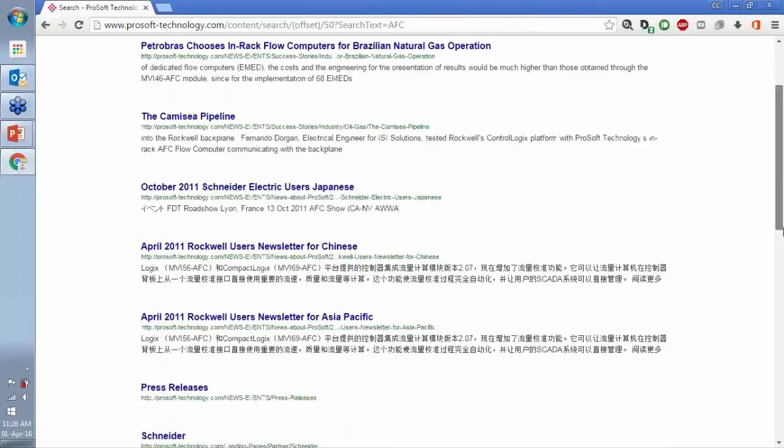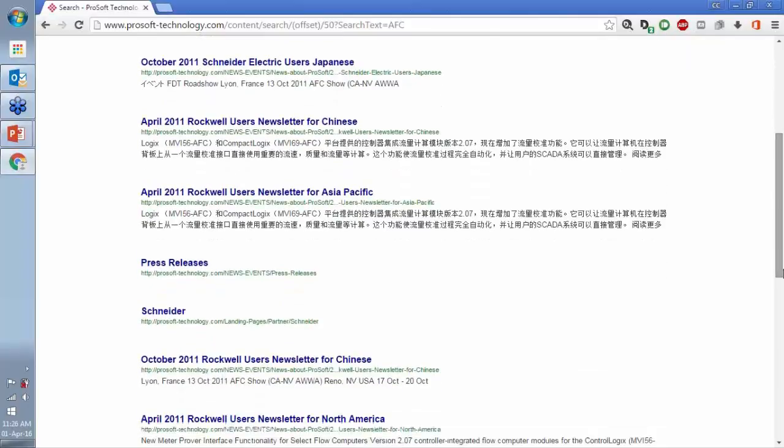Okay, that's another question. What is the connection from the EAFC to the meters, etc.? Hardwired or high-level communication? Hardwired. The EAFC itself does not come with I/O. That's a really good question, by the way. Standard flow computers have built-in I/Os, just enough to fit the capacity of the flow computer. The EAFC itself doesn't come with I/O. So what you need is standard PLC I/O, and the EAFC reads the I/O values from there. You would wire in your pulses from your turbine meters. You wire in your pressure transmitter and temperature transmitter readings into analog input cards, and all that will be transmitted to the EAFC via the backplane.